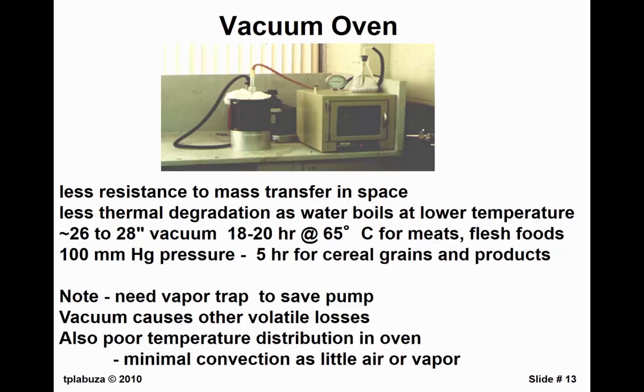Vacuum pumps don't like water. Those cheap vacuum pumps are vanes, and they get water on them and they're going to get rusty. Okay, and then eventually you're not going to have a vacuum in there anymore. It's not going to work, so that's not very good.